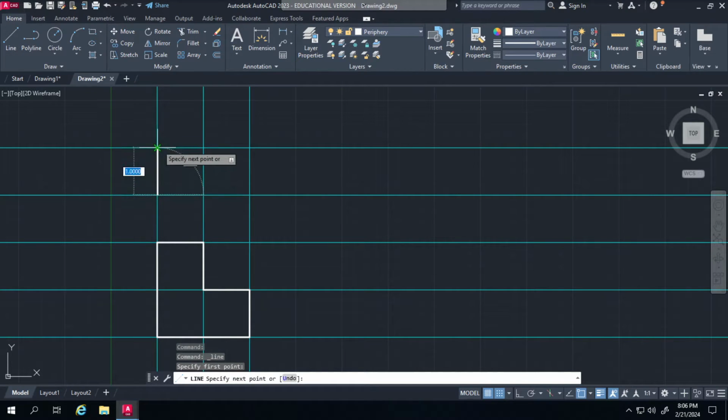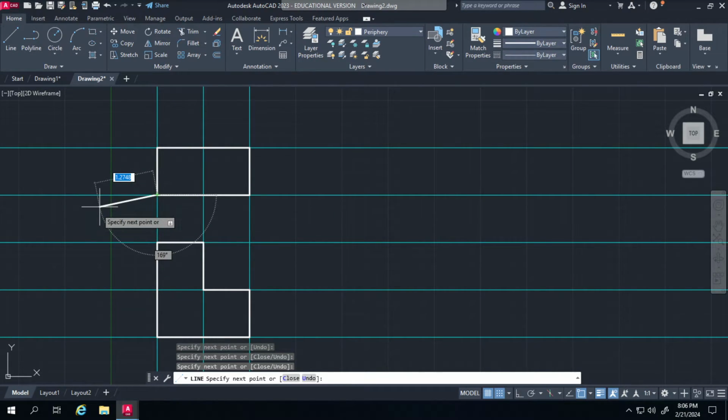Again, I'm using the intersections of the lines to help me determine what this will look like. This should be pretty easy. It's the 4 lines that would represent the outside of the profile. But see how this construction line helps us identify this little tip right here that needs to come up? So I simply go back to line and create a line from here to here.